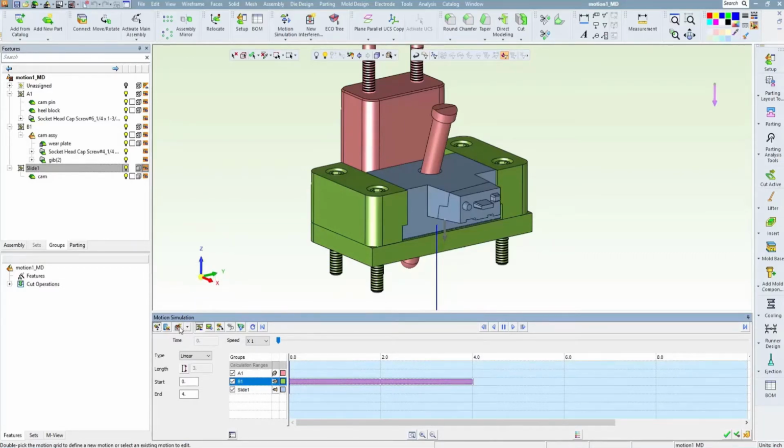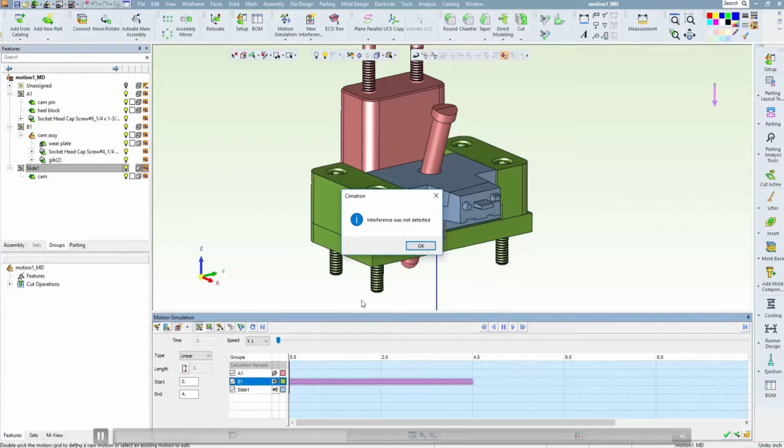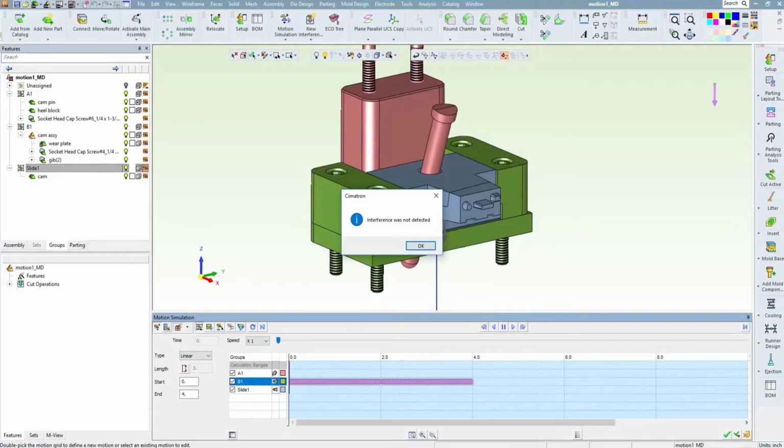But before the actual motion kicks off, follow one more rule, interference check. Run a static interference check on the parts as they sit. If any of the bodies overlap, the design already has a problem that must be fixed. Here we find out very quickly that the parts have no interference and so are good to go.